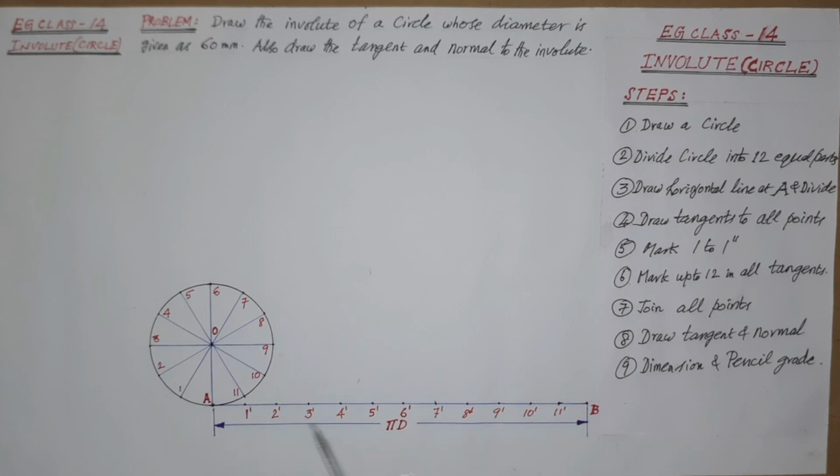Then divide it into 12 equal parts using divider or compass, since the circle is also divided only into 12 equal parts. That is 188.5 divided by 12 equals 15.7 mm each. There would be a fractional difference of balance while dividing, approximately equal to 0.1 mm only in total for the 12 parts. This is negligible and not measurable here since we are using millimeter divisional scaling.